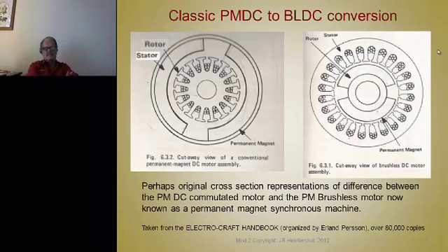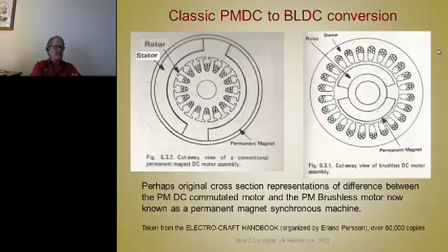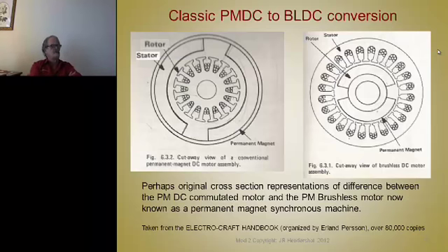In fact, what you concentrated on when you designed these brushless motors in those days was to get a high winding factor, high efficiency, low losses, good performance, and good torque versus amps. You wanted to keep the losses as low as possible, and you didn't really care all that much what the back EMF looked like. It wasn't important.